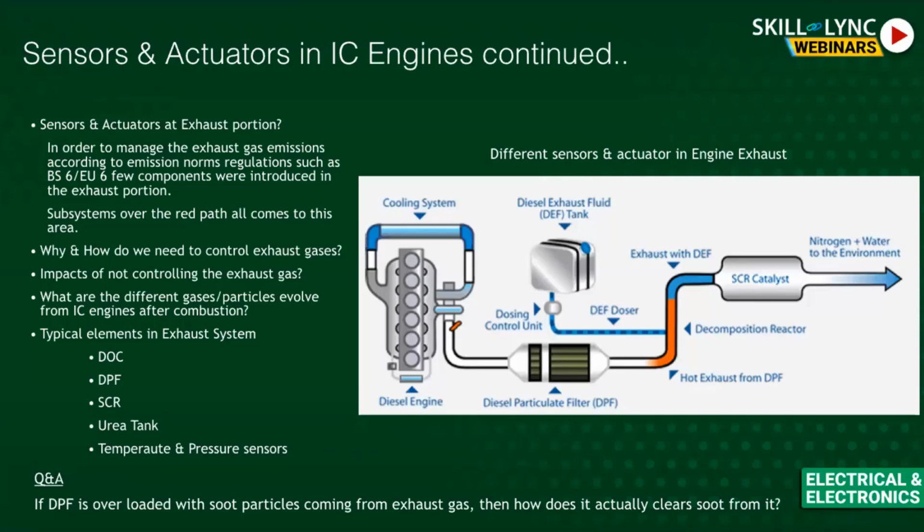This will get mixed with the exhaust air, and your exhaust will have dangerous nitrogen oxide components, which will get mixed with this. Just simply for understanding, call it NO, nitrogen monoxide, which is released in the exhaust, and NH3 is for urea. Both NO and NH3 have N's, right? After the chemical reaction, it will come out as N2 plus the other subcomponents. Compared to NO, N2 is a much better gas.